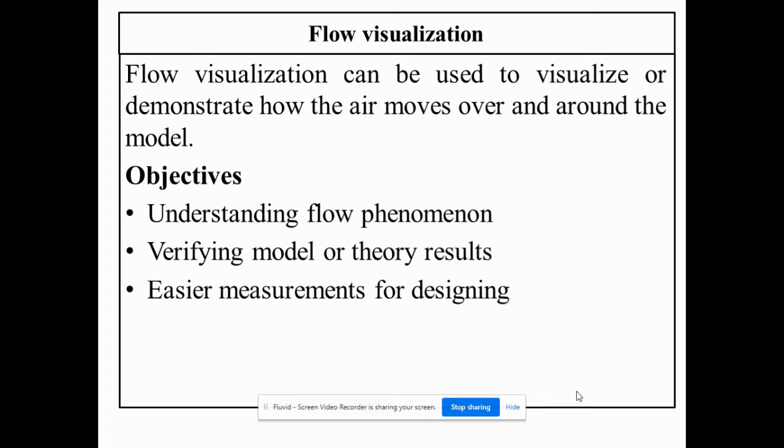For instance, if I want to have a simple airfoil, I want to introduce some kind of roughness or some kind of a tail or an attachment to it, so I can increase the lift coefficient. So I should understand what the flow phenomena are around the model, so that will help me in understanding the full flow physics, so I can go for any model or any designing of that particular structure.